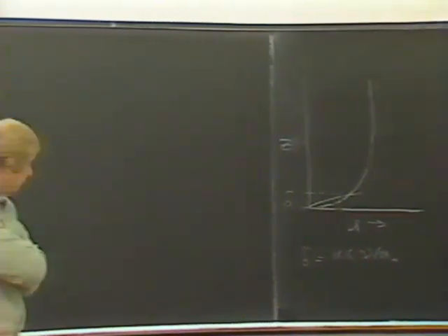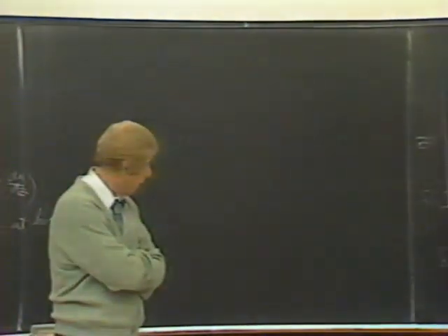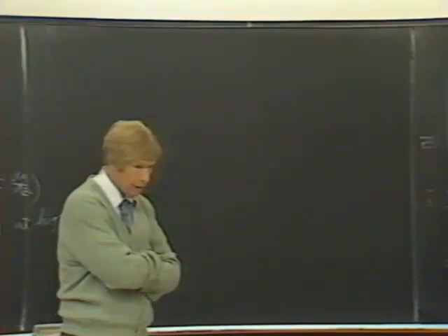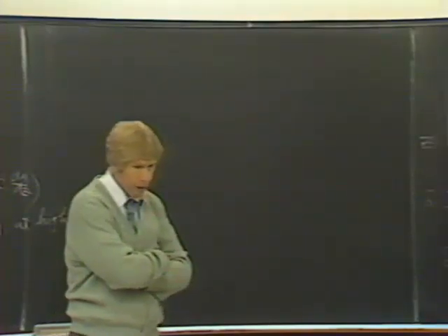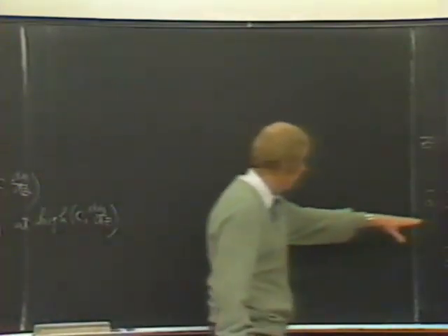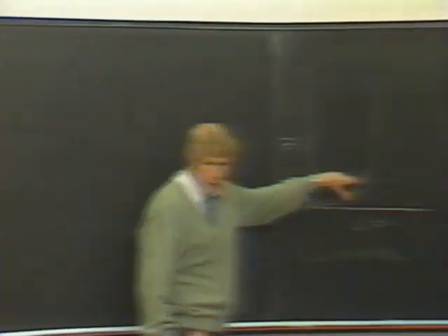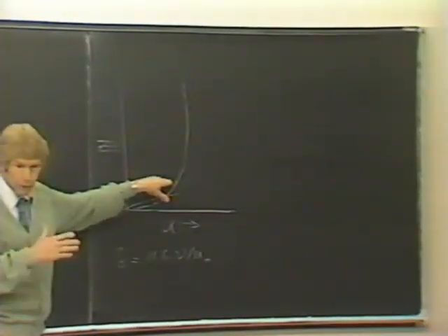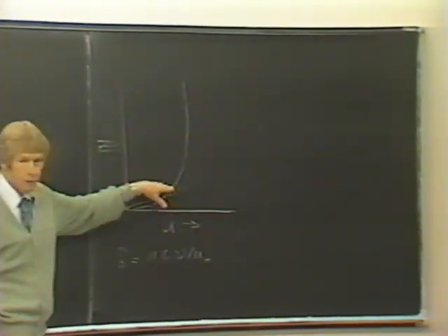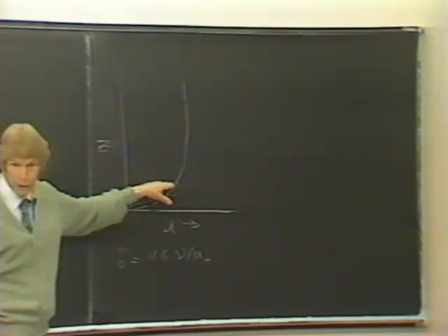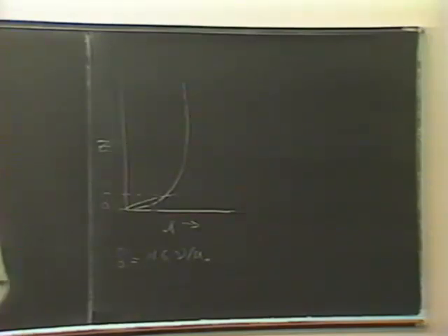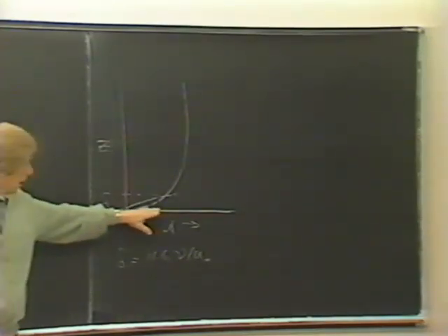See, we were talking about breakup of aggregates in the bed. So our flux to the bed now is the flux of those broken up particles. Follow me. In addition to which, particles that contact the bed may or may not stick. Some of them are torn off by the velocity gradient. Recall that I said early when we were discussing aggregates that the aggregates in suspension are free to rotate.